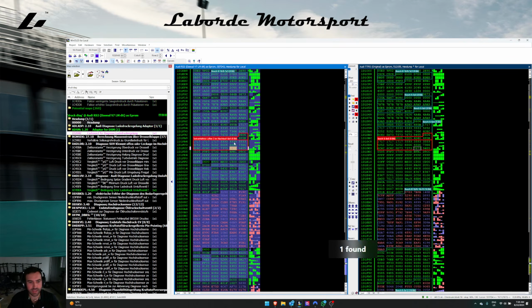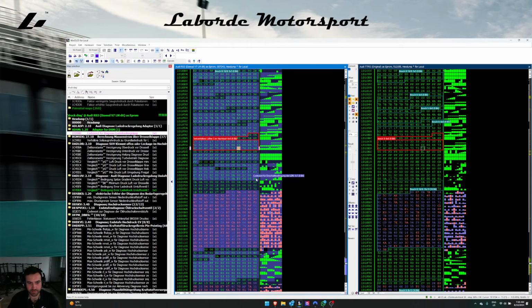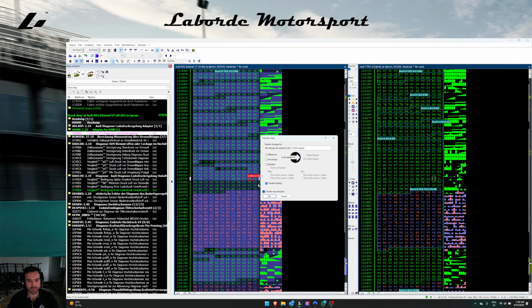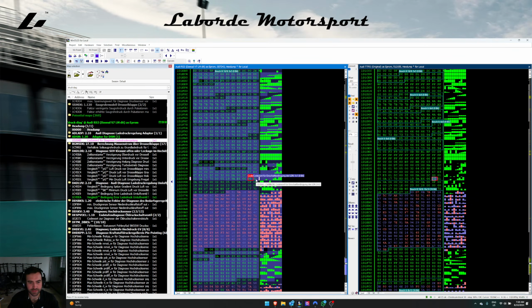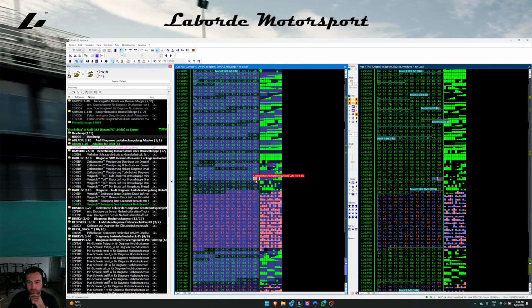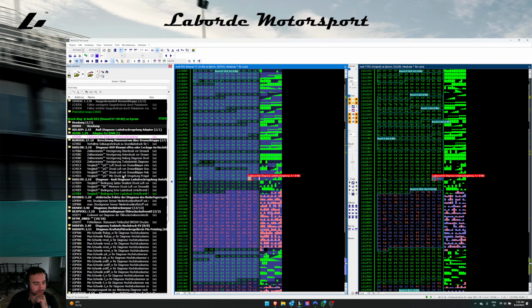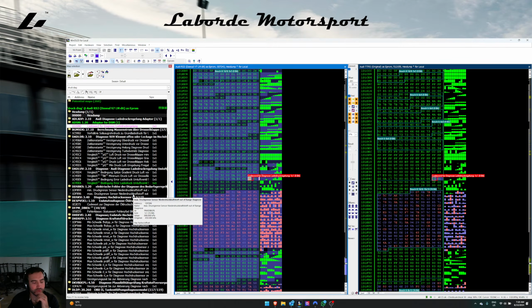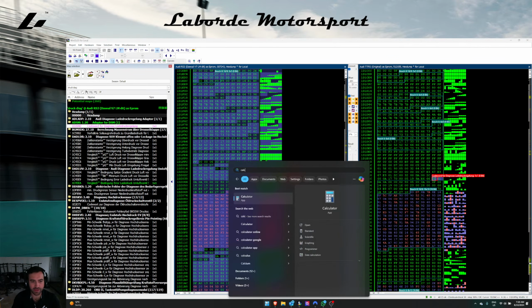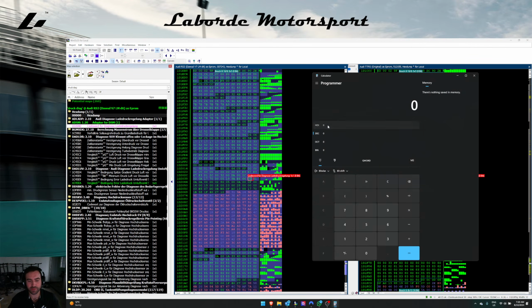So I'm probably going to disable that. Like I said, the only reason I'm doing that is because we're running an open loop, and I don't want there to be any throttle closure when we run over the internal 8-bit variable limit, which is 255 kPa. The reason an 8-bit variable has that limit is because the maximum value it can be in hex is FF, which in decimal is 255, right?